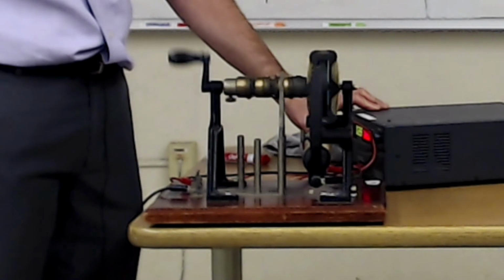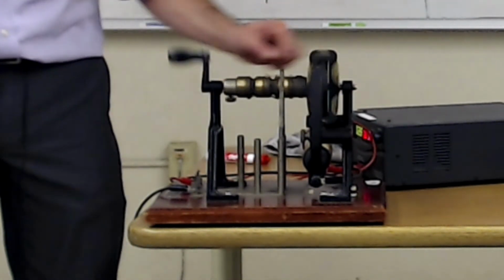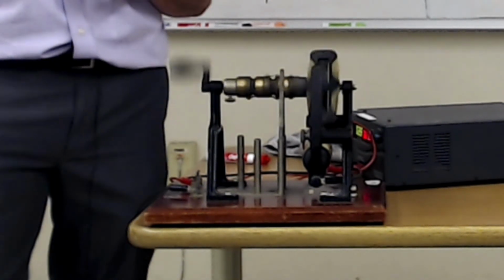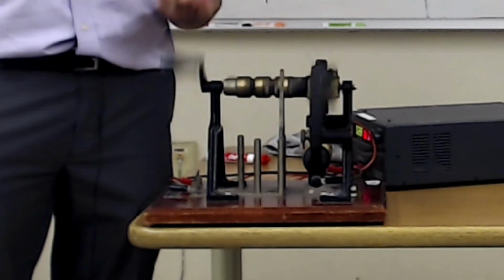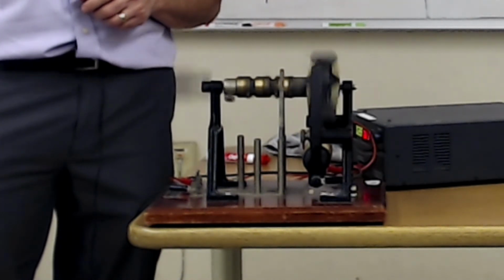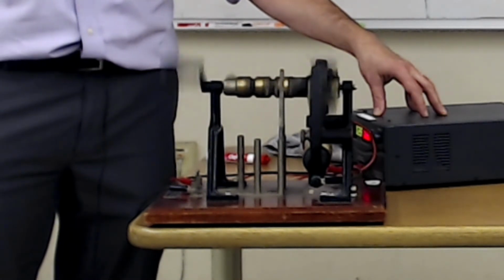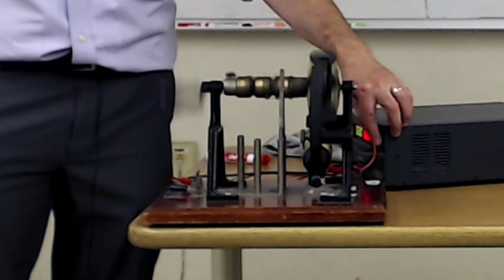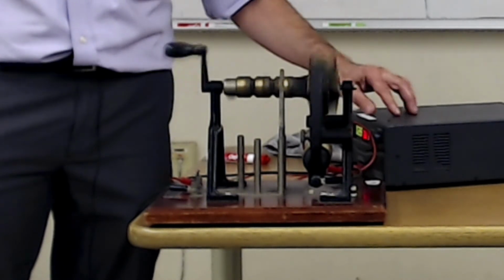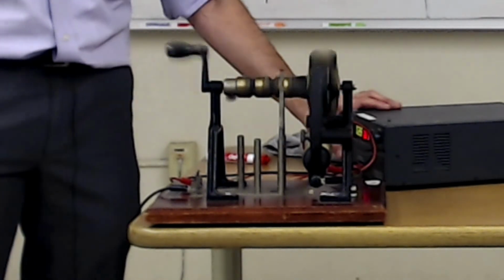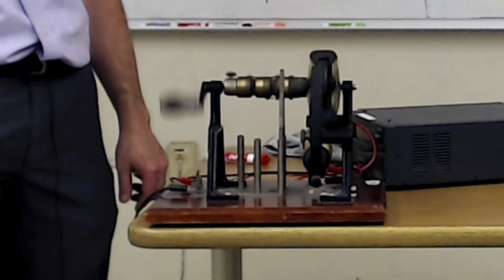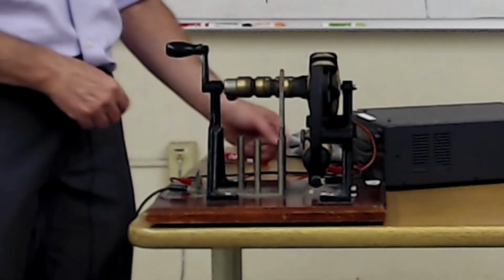I don't want to run too much current through it. And so it spins by itself. I've actually got 7 amps going through this thing and only 2 volts on it. As a result, it's spinning pretty darn fast. With my other power supply, this thing won't spin it fast. So let me turn it off. And let me disconnect this from the power supply.